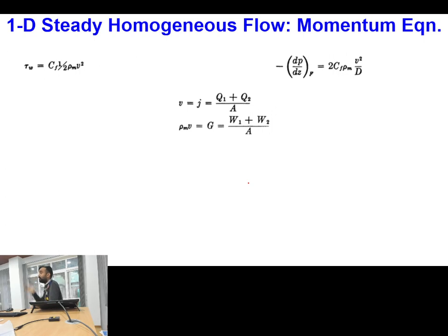So we will not be able to predict the actual velocity profile at the wall. If we are not able to predict the derivative of the velocity profile at the wall, then from theory we will not be able to find the value of wall shear stress. So we have to look to certain other forms to determine the wall shear stress whenever I am applying the homogeneous flow theory, particularly based on one-dimensional approximation.